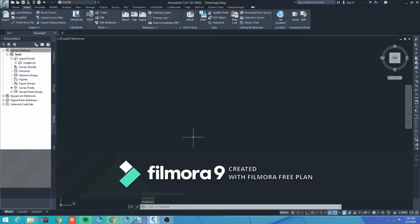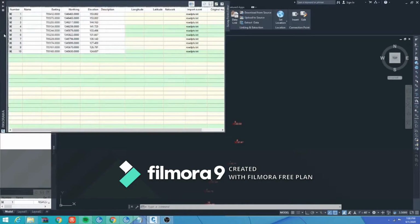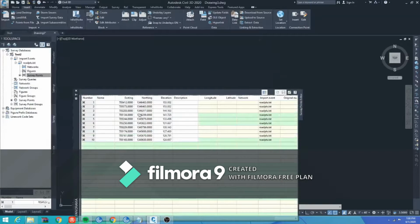If I zoom in or double tap on my scroll mouse, you can see that these are the points that we have just imported. You can view the points by going into Survey, the test file, road points text, survey points. You can view it down here, or by right clicking and hitting edit points, and we'll get a new window in which we can view our data.